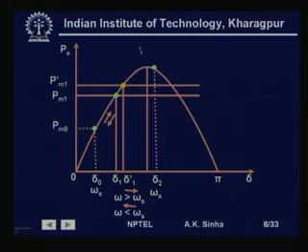Now, the speed is becoming less than the synchronous speed. So, delta with respect to the synchronously rotating reference frame is going to keep on reducing. So, we will get delta reduced once we have reached the synchronous speed. At this point the rotor will start decelerating and delta will keep on reducing.